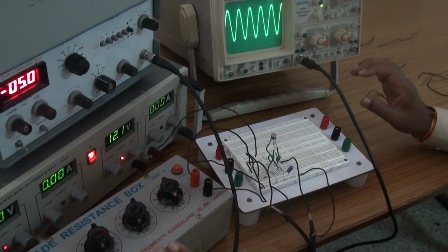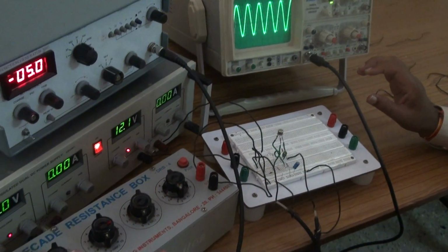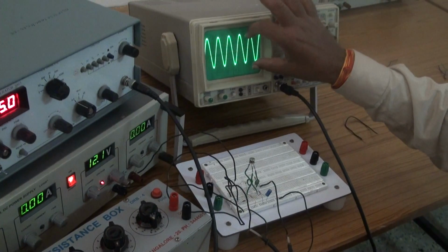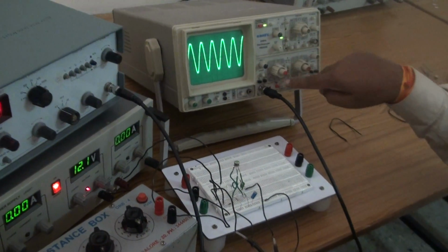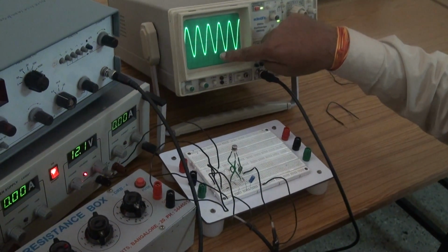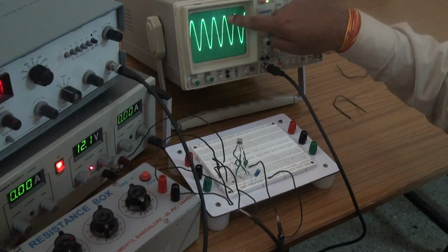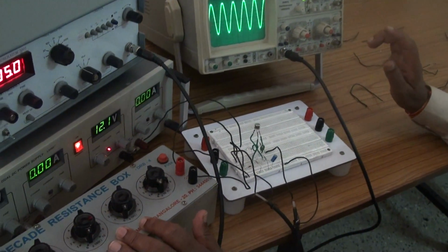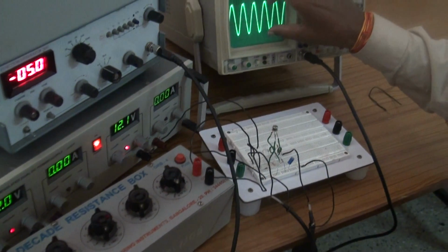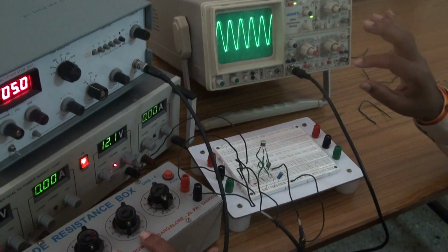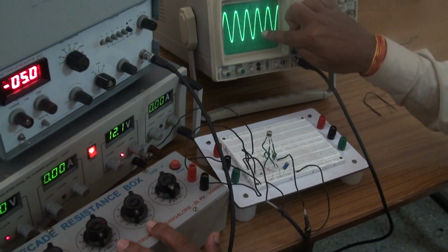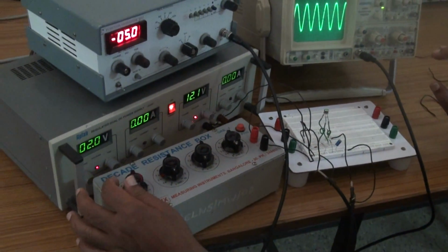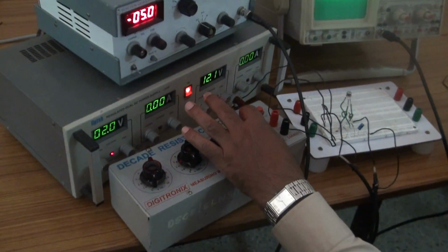Okay, start. As I told you, the DRB value should be 0 such that we are going to have some output voltage. Now we can count and check the number of boxes. Here to here we have 4 boxes. Now we have to increase the value of resistance such that it becomes half of this value. That is, we have to adjust the DRB value such that it becomes 2 boxes on the screen. So we have to start adjusting with smaller values.